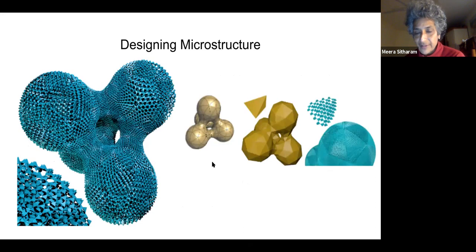And so this is where the rest of the story is going. This just shows a picture of an object that someone wanted to model. The standard classical way they do it is to split it up into tetrahedra, and then we fill the tetrahedra with microstructure. Of course, the microstructure that we choose is these corner-sharing tetrahedra, which have built-in rigidity properties. We can sew them together across these boundaries using a simple technique without losing these rigidity properties.